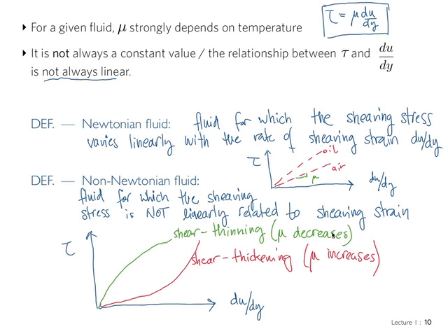Blood is like that as well, but the effect is quite more mild. And so really in many approximations we can just say it behaves like a Newtonian fluid, and that's also useful. It depends on the magnitude of the shear stresses that are involved. And so in many studies of blood flow, people will assume that it's a Newtonian fluid, but it really isn't. So you need to bear in mind that perhaps in some situations the non-Newtonian behavior becomes important.